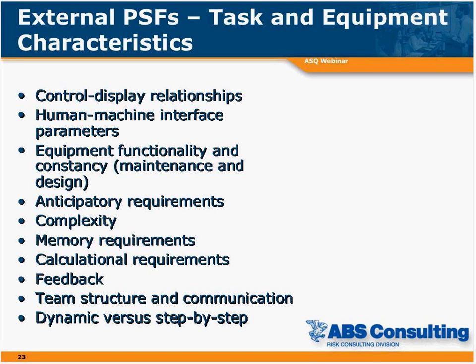We have a category, equipment characteristics. The entire interface. How easy is the equipment to use? Is the control display in the same units as the procedure? You have to climb a ladder and hang upside down practically to operate a valve. How do I interface with that valve? These are things on this list that we need to take into account.